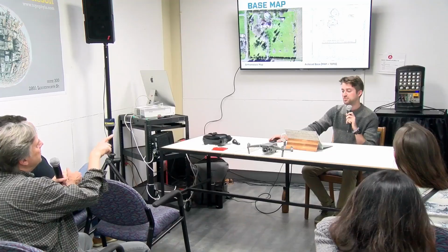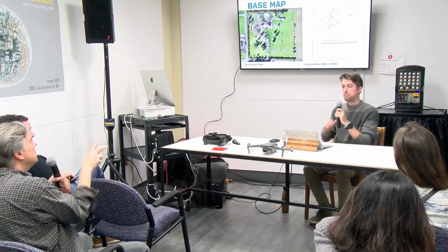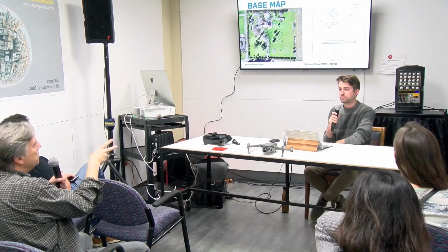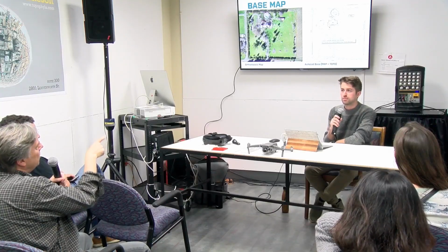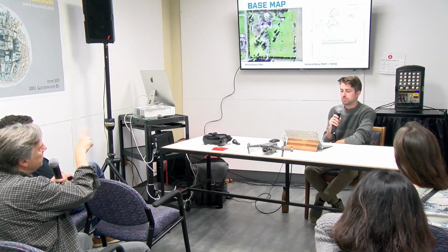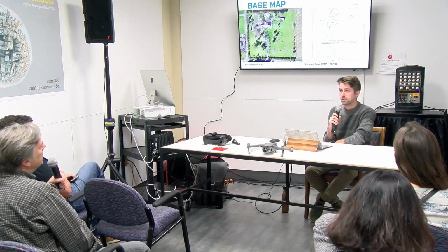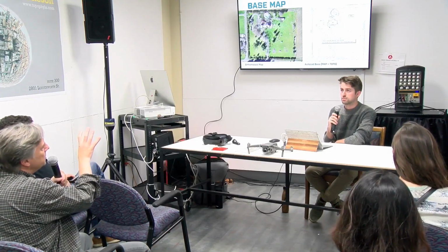So in that AutoCAD base, the contours could either be from the drone, but all the rest of the drawing you're tracing in on top of the photo? Yes, correct. And do you do anything to the photo? Do you turn it to black and white before you do your tracing, because you're tracing over a photograph essentially. Yeah. So I just overlaid it in AutoCAD, faded it out so it's transparent and I could see through it, and then traced over it. So it's as simple as that.